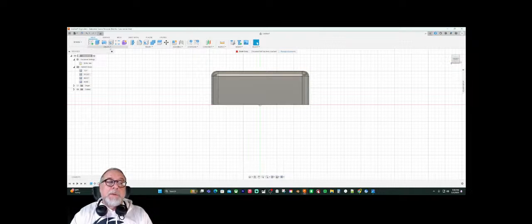So what we're going to do is something a little interesting. We're going to take a cylinder and put it on the same plane as this side of the ring. Now I've got to figure out where the center of my cylinder is, so that when my cylinder is extended, it's going to hit probably right here on these edges, because then I'll round these in.